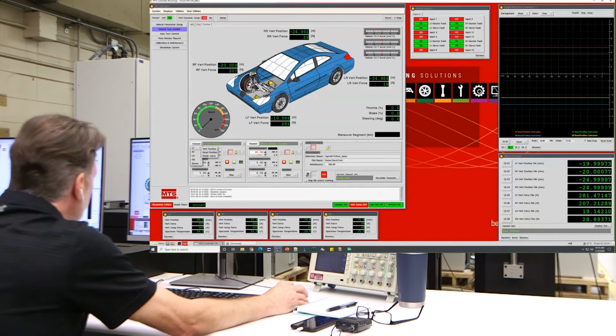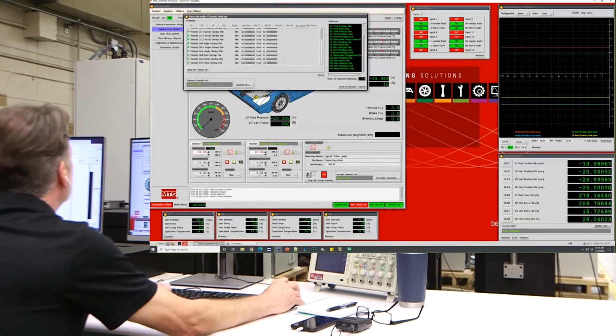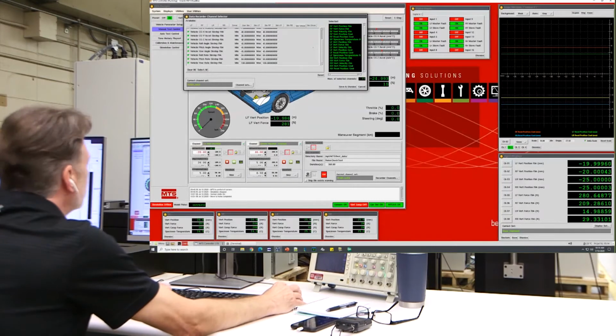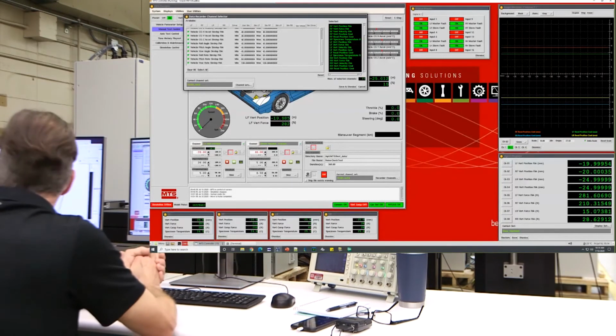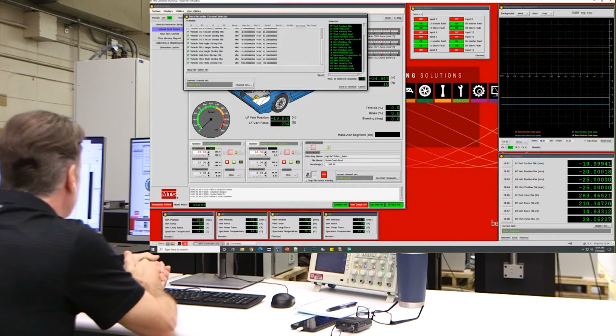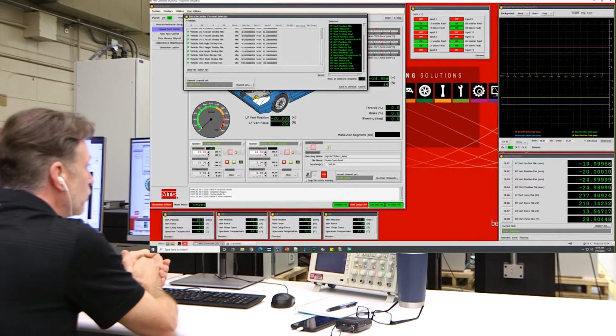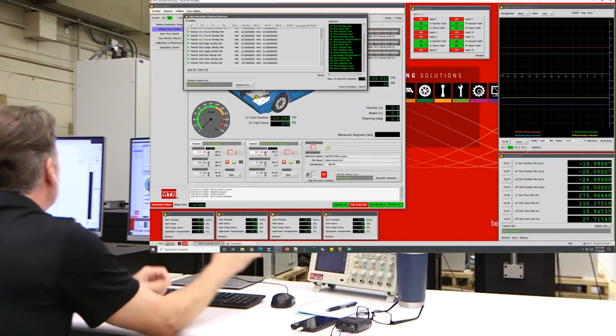I've got the ability to turn on the data recorder, and I'm going to quickly bring up a screen here. These are all the channels that we can collect. As was mentioned earlier, one of the components required to build an mHIL system is a very high-speed digital link between our dSPACE HIL simulator and our control system. This gives us the ability to send a number of signals in addition to the required signals for the closed loop, the position and force.